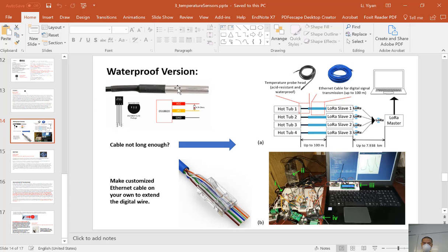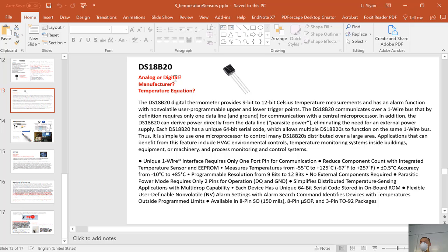So what's inside is actually this little thing, the DS18B20. That's a digital temperature sensor that has been very popular. The reason it's very popular is it converts temperature directly to a digital signal. It's called a one-wire temperature sensor. Everything is encapsulated into this little package, and when you connect this one to a microcontroller, it's directly digital. It's amazing. So temperature to digital, no other amplifiers or anything required.